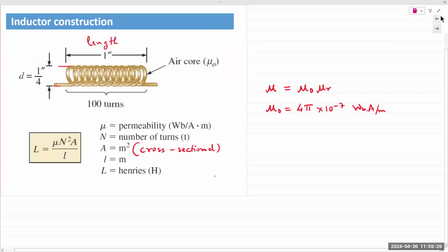If we go back to the slide, I would like to point out something else. You have this coil, right? This coil, you have two ends of that inductor. If you take the two ends of the inductor and you measure the inductance, you will receive some value. If you place it across an ohm meter and you measure the resistance, you will again receive a value. Because the coil, again, is made out of some metallic material, it has some resistance. Real life wires are not ideal. They will have some resistance. Good quality inductors, that resistance is 5 ohms or less. Lower quality, it's like hundreds of ohms, okay?